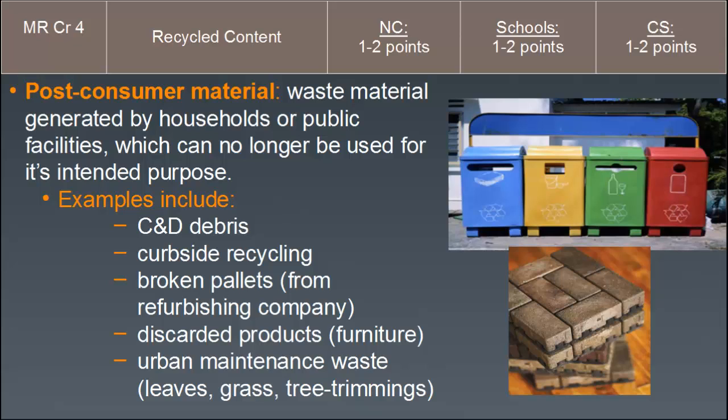Keep in mind that LEED version 3, Building Design and Construction, does emphasize post-consumer recycled content over pre-consumer recycled content. That's why only 1/2 of pre-consumer recycled content is in the equation. It is a total of the two added together, so both are important. It's just important to know what to emphasize as you're specifying material and educate manufacturers on what is important to you. That's how the market is transforming through the LEED rating system in these buildings.